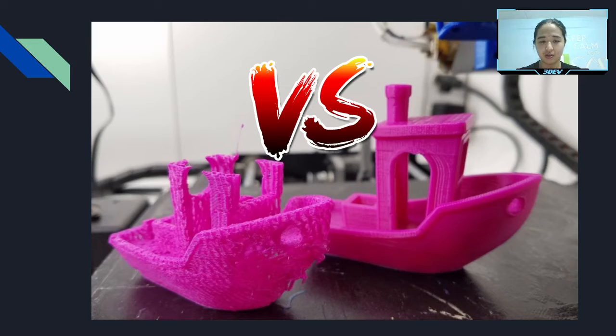This one we normally call under-extrusion, and we have a little bit of overhang over here. Overhang is normally caused by the temperature. Apart from that, if you have a look at the Benchy at the back, you have a nice smooth surface on your model. So you can see how you tune your slicer may affect your model. So this is the importance of the slicer in 3D printing.